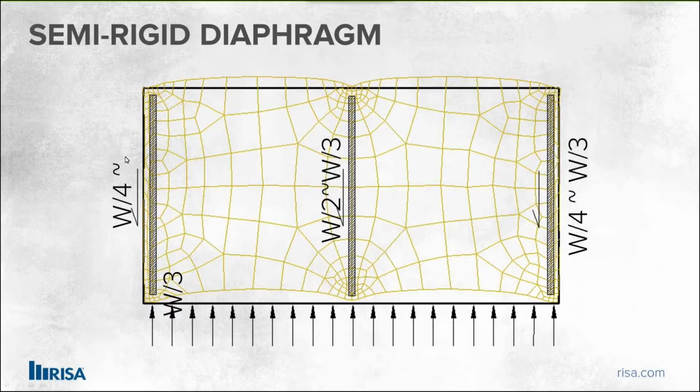One thing to consider as we start this semi-rigid diaphragm topic is that you can see one thing the other two did not have: we have a lot more elements in our model. We put plate elements throughout this, which means there's more complexity. We now have however many plates are shown here, as well as the wall elements that are also plated. So it becomes a bigger model, just inherently. More accurate possibly, but you may lose that in speed or modeling time. So you have to consider what you need for each one.